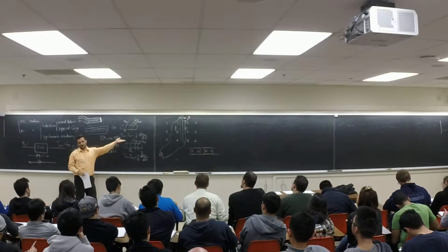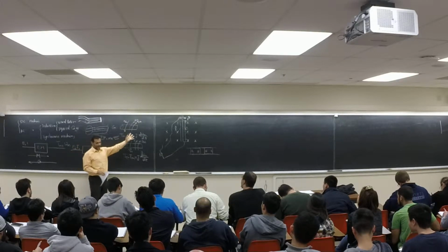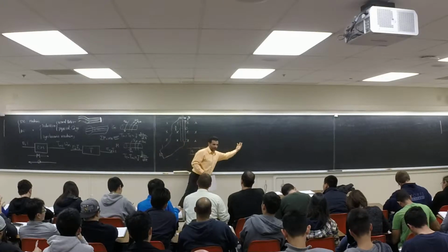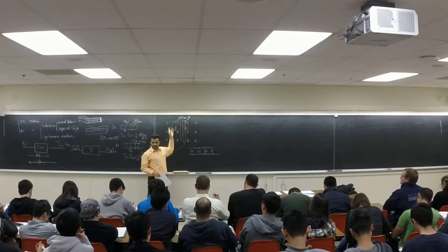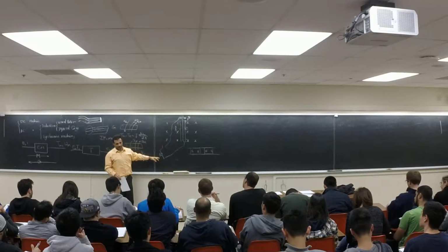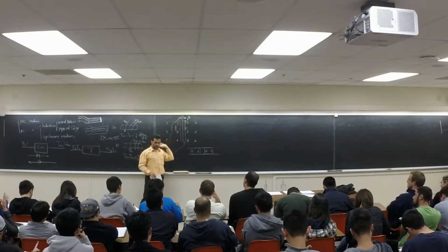This is a generator, okay? It's not a very good generator. You use some mechanical power, you move this one, and what is going to happen? You're going to generate electricity. If you close this switch, you're going to have a load here. If you don't close the switch, you only have a potential here, but it's not generating any voltage.